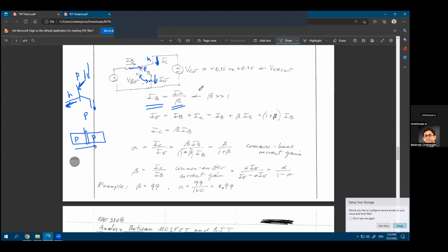Okay. But as circuit design engineers, all we care about is eventually the equation, and this is where most of the circuit books will start. But as you go to a semiconductor physics class, you'll probably understand this better. But I just tried to give an intuitive understanding of what is happening: that you have a lot of carriers flowing from your emitter to the collector. Some of those carriers are getting recombined with the other type of carriers inside the base, right? Because the majority carriers in the emitter are different from the majority carriers in the base, because they are different type semiconductors.